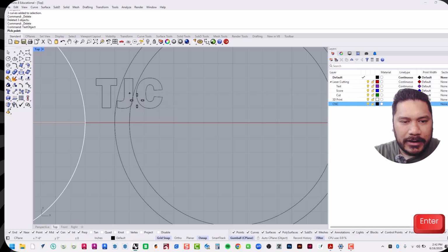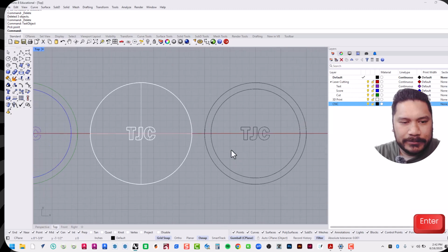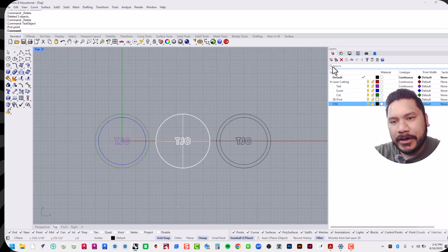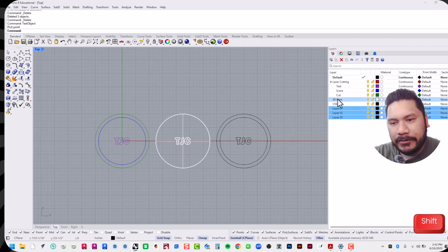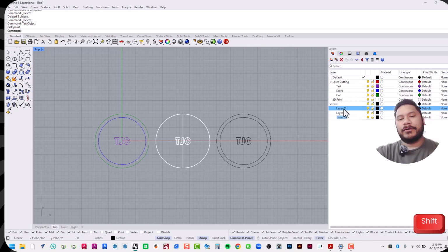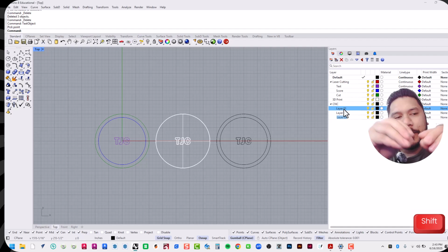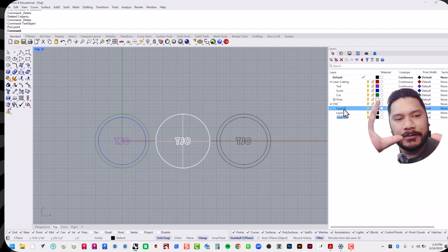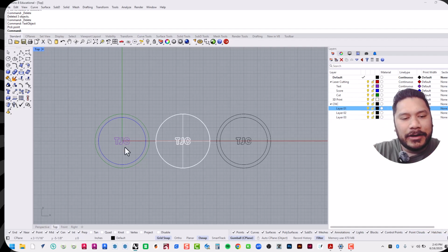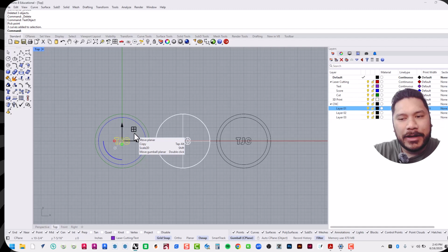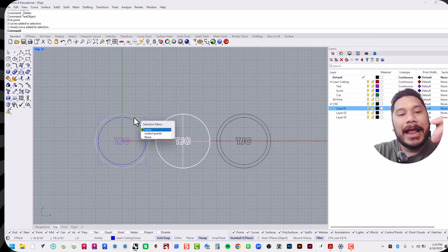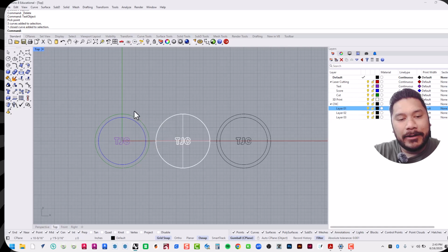And whenever we're fabricating, for the most part, we want to work our way inside to out. So let's say with the laser cutter, we want to do the font first. We want that to be engraved first, and then we want to do this score, and then we want to cut the whole entire thing out. Okay. If you cut the coaster out first, what's going to happen is you have a sheet of plywood in the laser cutter, you cut out that perfect circle. That circle is going to drop below the top surface of the rest of the plywood, right?